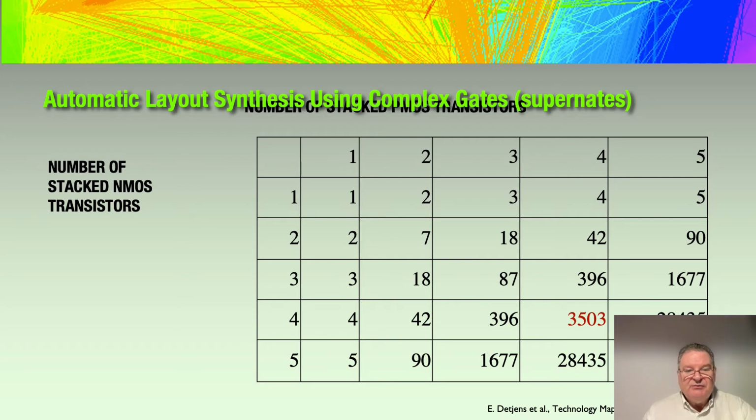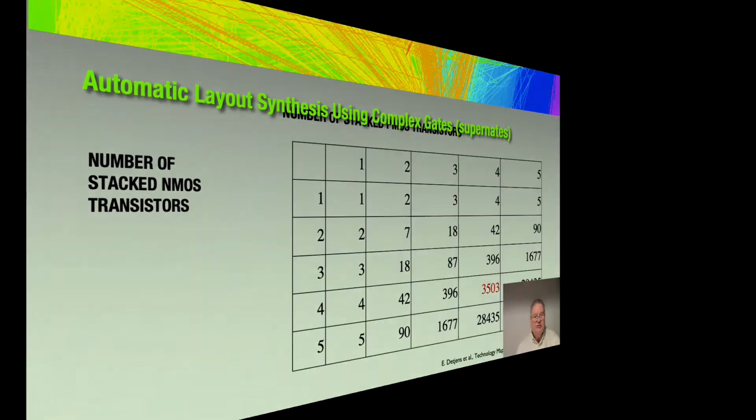It's in red, more than 3,500 different options. And we see nowadays that cell libraries normally have less than 100 functions, only 3 sizings. And so this reduces the space to do optimization of the logic, and consequently the optimization of the number of transistors.